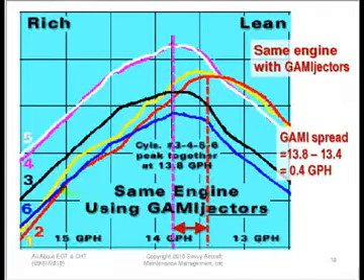But again, if you look at this engine, and this is now an excellently tuned engine that will run very, very efficiently and very well on the lean side of peak, you'll still notice that there's a big spread between the hottest EGTs and the coolest EGTs. This is the thing we were referring to as diff, and it's quite large. If you looked at this on a graphic engine monitor, you would not see a flat top.